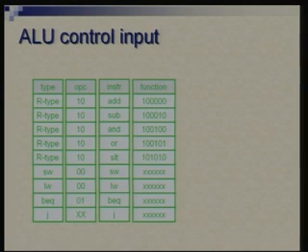So the third column shows individual instructions, and the last column shows the function field. The function field is not to be seen for instructions other than R type instructions. So I just put don't care there, because in those particular bits we have something else. We have address offset or some part of address. They are not specifying function bits.